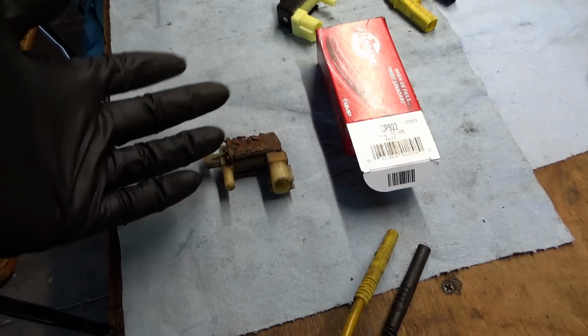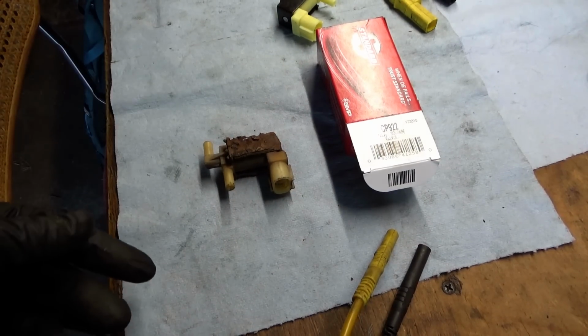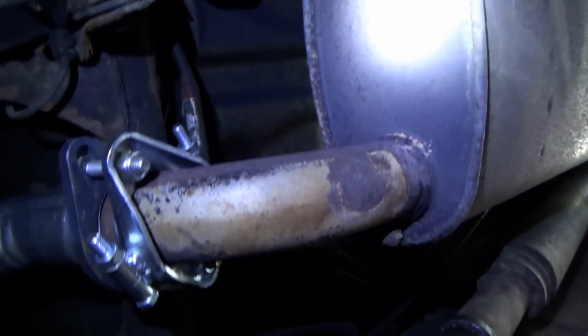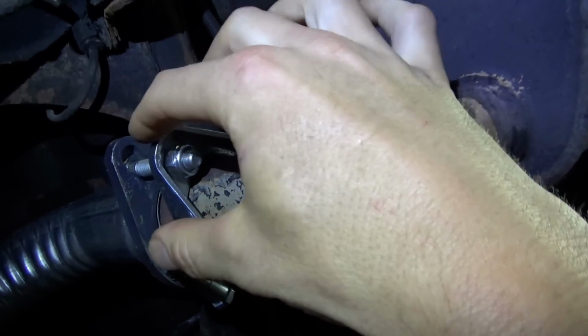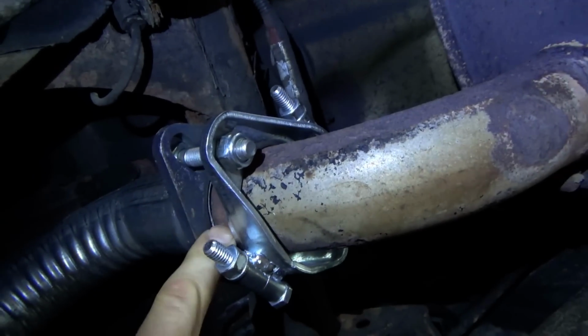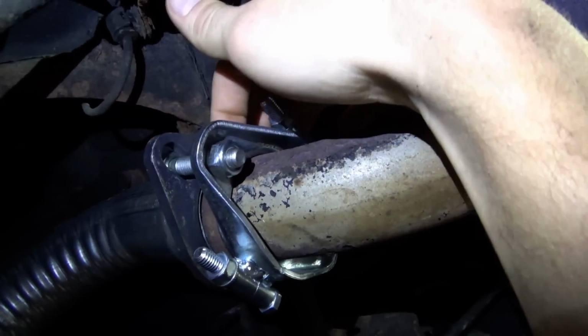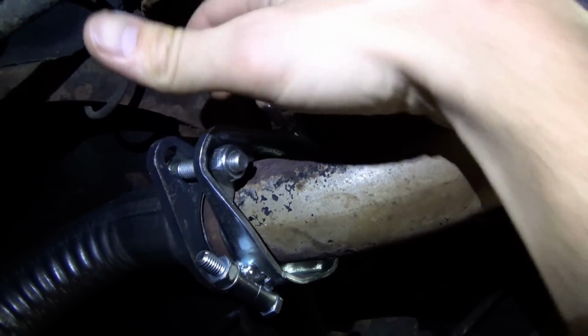Customer also approved a new tailpipe, so we'll get that done as well. Brand new tailpipe installed on the 4Runner, and it took a little bit of creativity to adapt it to the existing elbow because the flange rusted off of there too. So split flange, 2 bolts, and a pipe adapter that will basically go into here and into there.